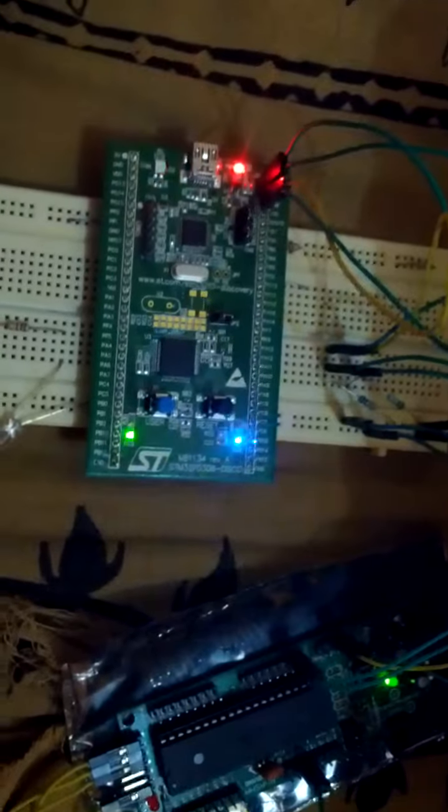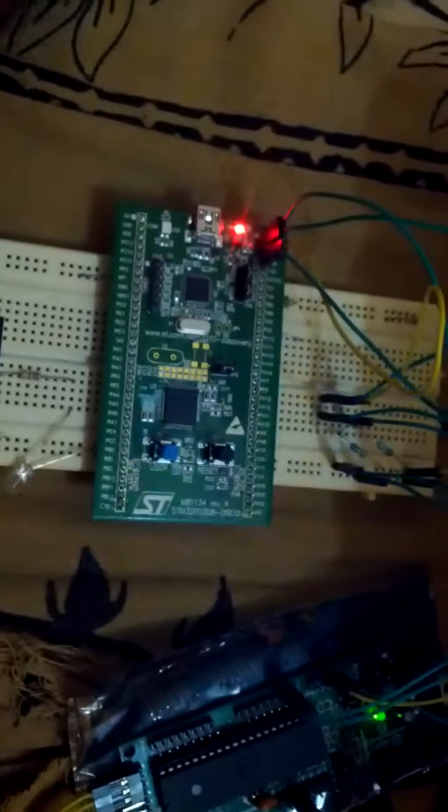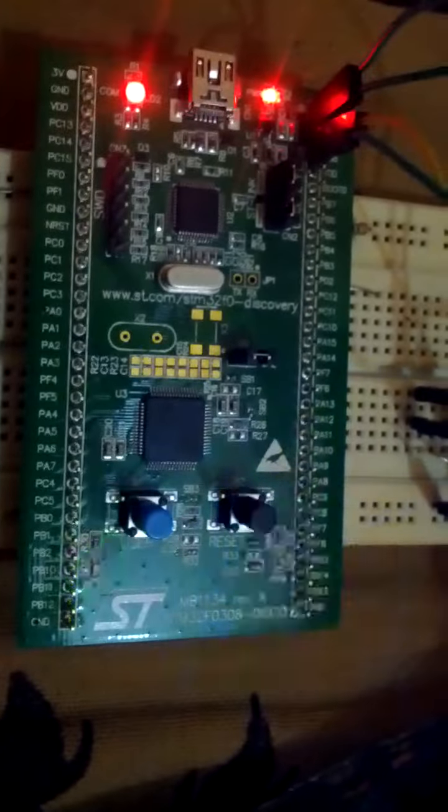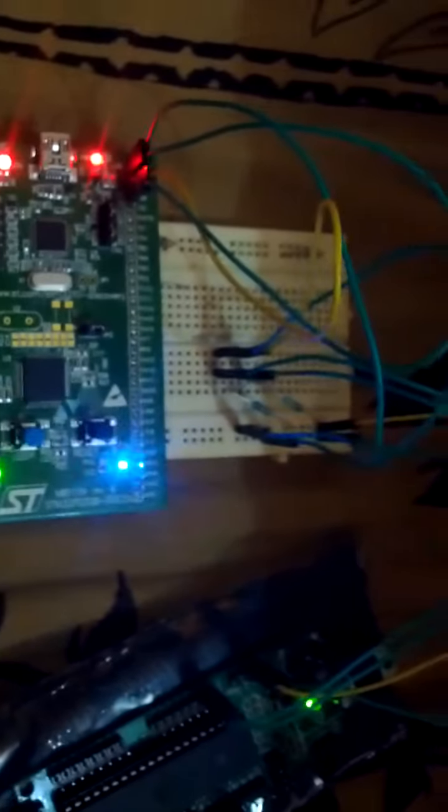The board is STM32F030. You can have a close look over here at the discovery board. Here I have used the connection like this. The slave is taking the 5 volt supply from the master itself. This yellow line is the 5 volt supply, the green line is ground, and here I have made the connection as per